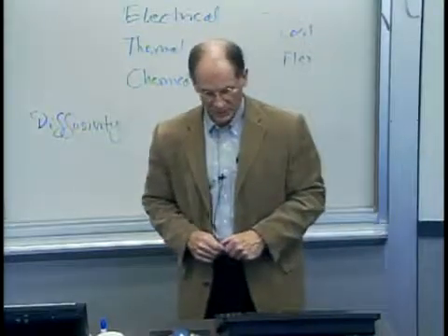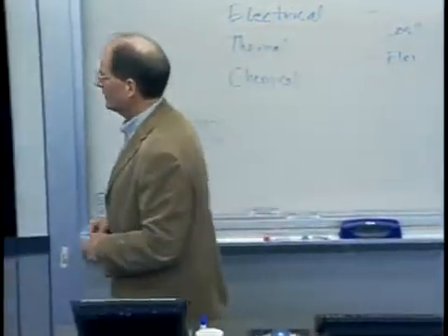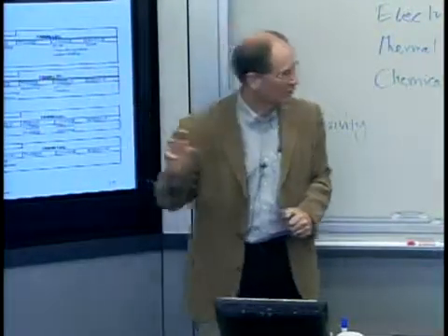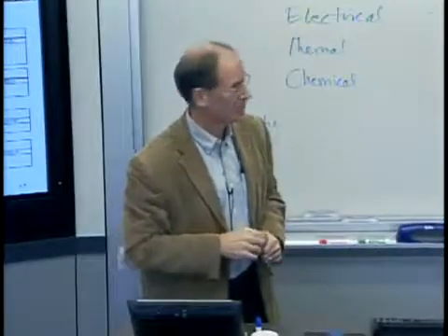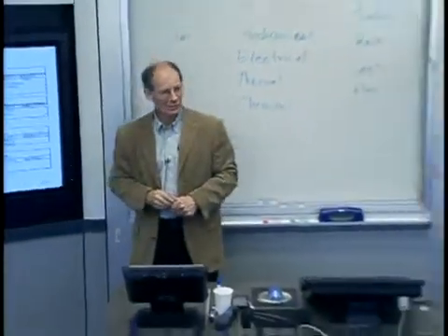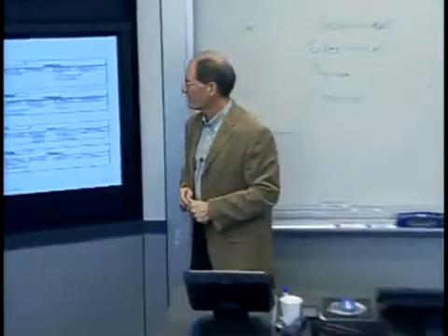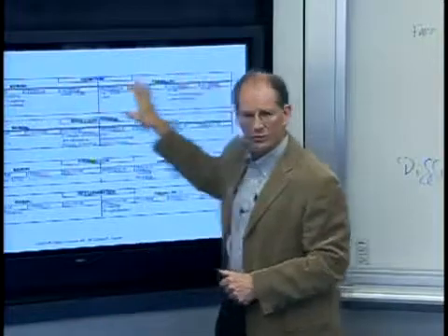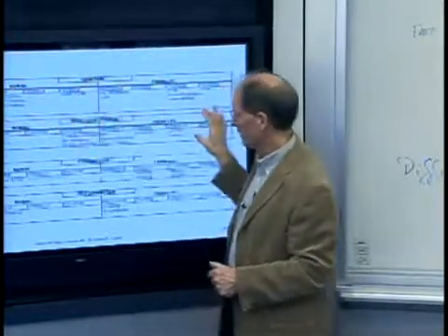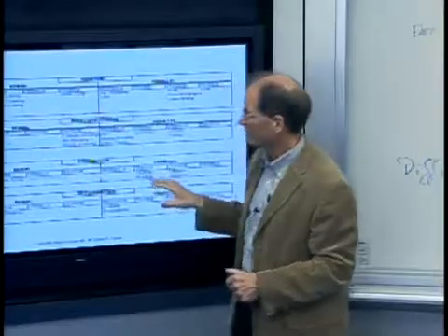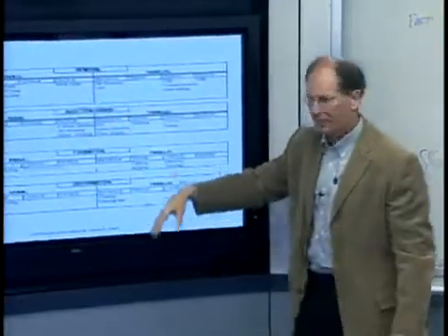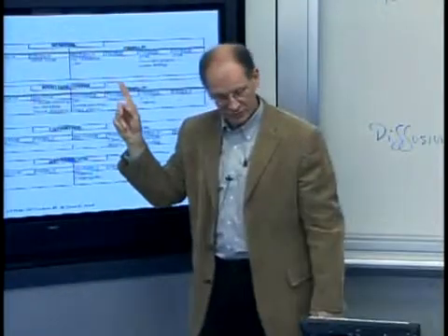Now this eye chart is an attempt to take this entire taxonomy and populate it with some examples. Some of these are no-brainers, and some of them could be a little bit controversial. Across here, this is the removal mode of transformation, and here's addition, and here's formation, and here's deformation. In each case, it's divided in half with serial and parallel, and then four different energy sources. So you look at each one and say, where's my favorite process?